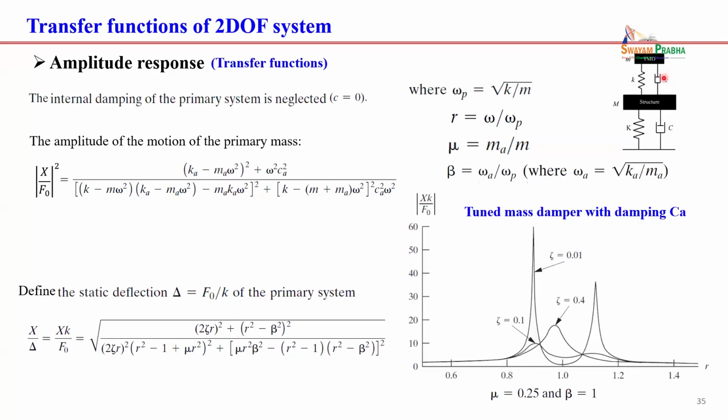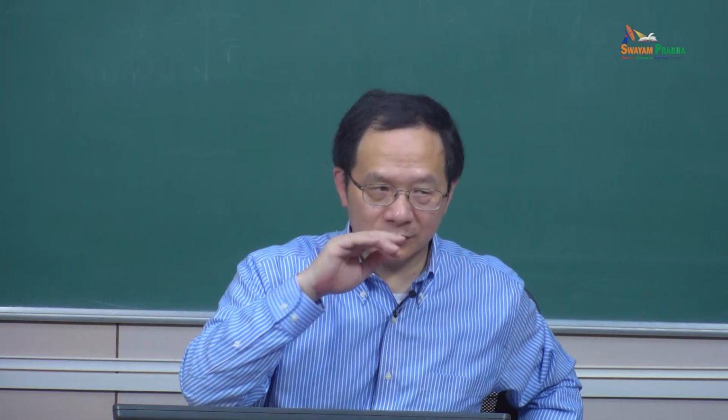The best damping was published, discovered by Den Hartog in 1946. I didn't write the equation here. This is a closed form solution for how to tune this damping, and also how to tune this mass. This is why, for the tuned mass damper, you need to tune to exactly one frequency. Such a phenomenon can be used for offshore structures and wind energy control.